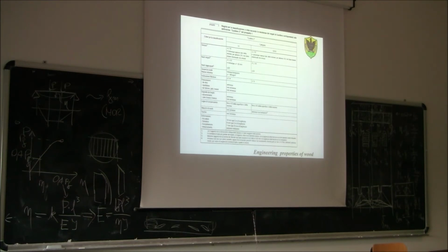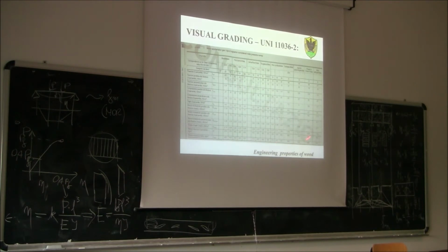Is it clear? Okay, now, but what do S1, S2, S3 mean? So far, we just know if this piece of wood is S1, S2, or S3. What is the actual strength class? You see, there is this regulation in this table saying that, for example, as we said before, spruce from the center of Italy, so Abete Italia. S1 doesn't have any class. S2 class C24. S3 class C18.